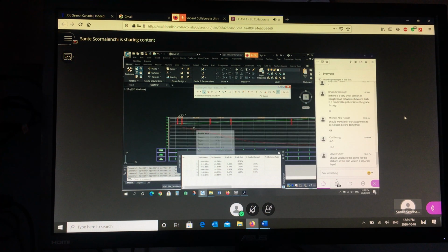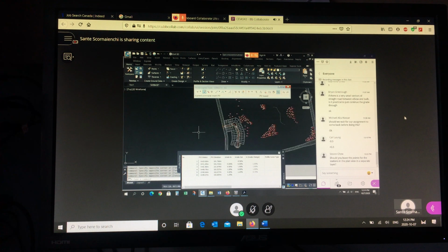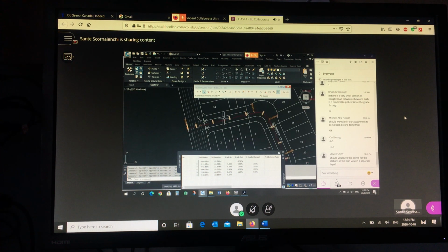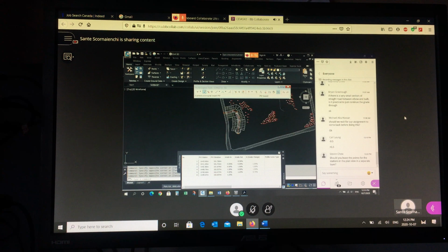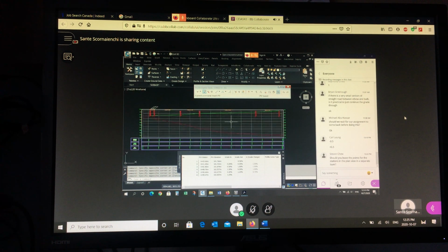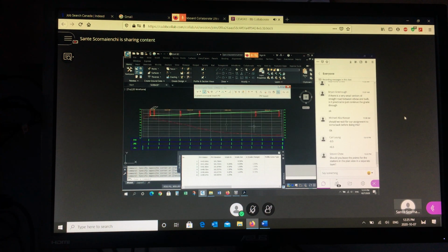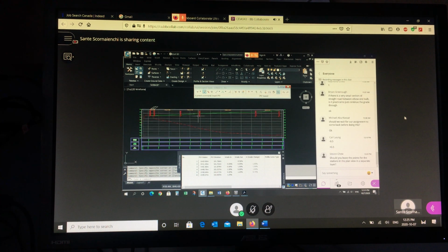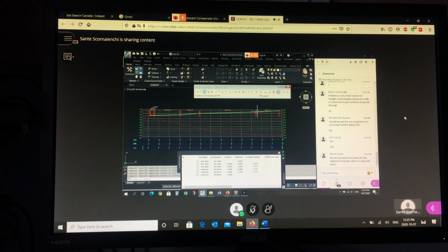Most of what you do is in the atypical things. What happens on your standard right-of-way, what happens in here is very quick. What happens between here and here is very quick. Just like you spending time in the crescent and the cul-de-sac and the intersection in your plan view, you're going to spend time in your profile at the intersection, at the elbow, and at the cul-de-sac. What happens between those atypical things is pretty quick, pretty standard stuff, right?